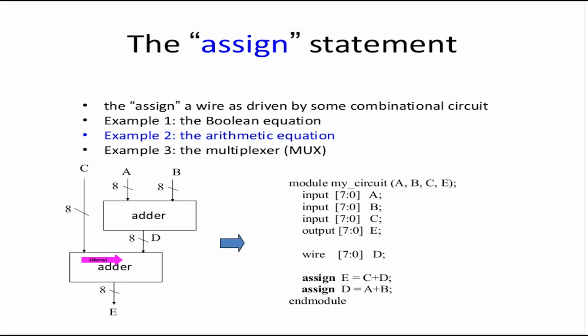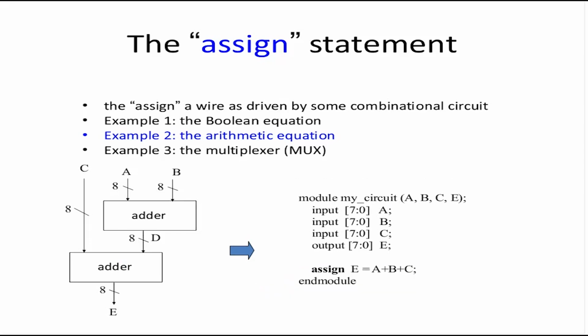The tool very well understands that irrespective of whatever order you write, reordering will yield the same result. We could also write assign E is equal to A plus B plus C. And again, depending on what kind of adders your technology library contains, the tool will implement it. If it doesn't contain adder circuits as standard cells, then it will again use AND and OR to implement it.